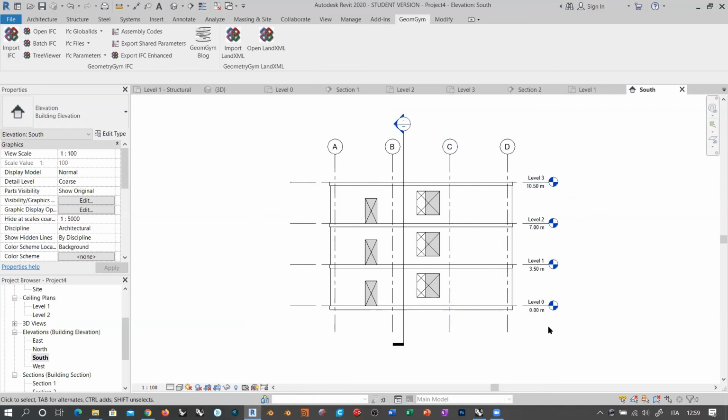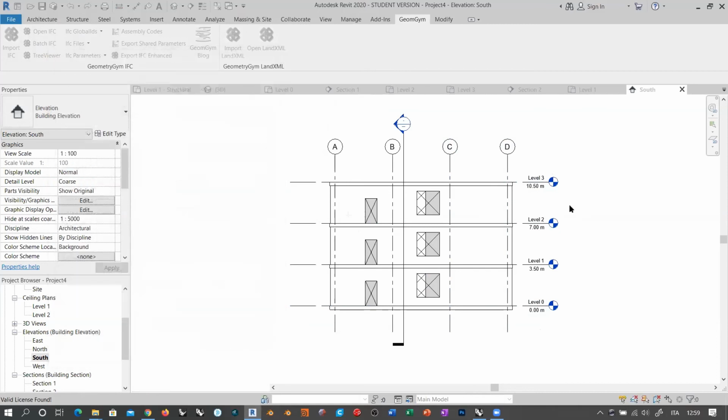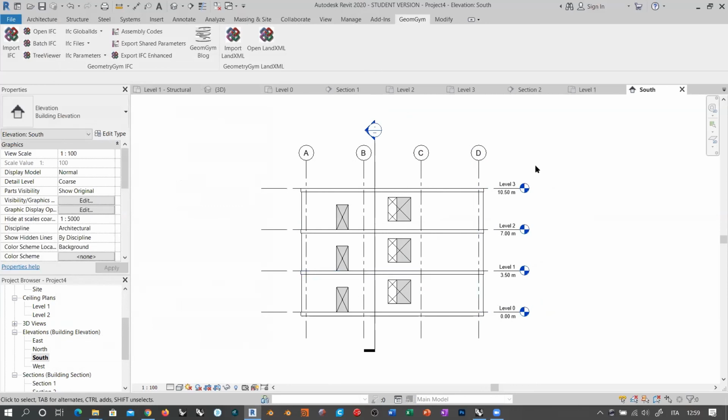has been maintained because the only thing that gets changed basically is the level height. Remember, from the IFC import interface, what is adjusted is, where is it, existing Revit level elevation. This is the only thing that gets updated. So these levels already exist. If you change the elevation of a level in Grasshopper, then it will be updated. Okay, but this is not the case. So everything regarding the visual aspect of these grid lines and levels has been kept.